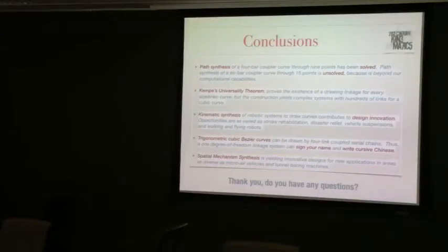So the Bezier curve drawer. Yeah, it's one linkage per segment. Four links, and it'll draw most of the Bezier curves. It has to have a pretty high frequency component to not be able to draw it. Cubic curves typically don't have that high of a frequency component. So if you wanted to do this with one real mechanical linkage, you have to accomplish two things. One is the lengths of the links need to be variable.